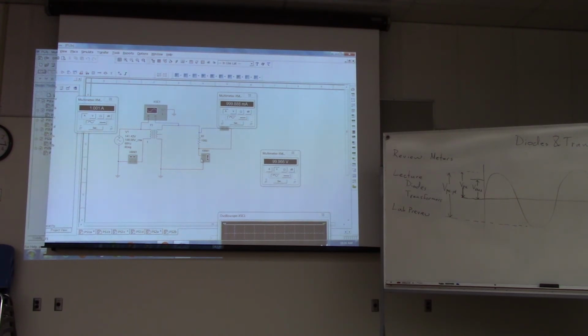So what happens is that when we're measuring low resistances, we have to be careful that we're just measuring the wires and we're not measuring the leads that are connected to the DMM themselves, right? Because the leads are just wires and we're measuring more wires, so you kind of have to figure out what's what.